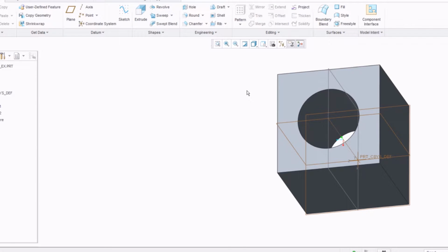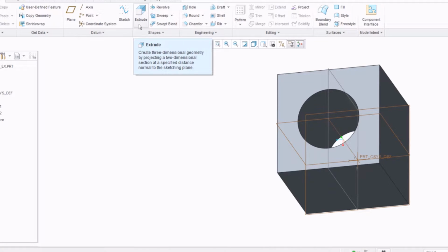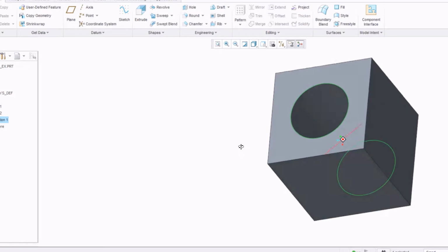Okay, so I've shown you the first way of extruding, but there's actually a second more useful way. Which actually, I think I showed it to you by accident, but you'll see it here. The first way I did with a sketch and then an extrude, and you'll actually see that it created 2 features in the tree on the left. The second time, I completely forgot to let you know I was doing it. I actually just clicked the extrude button and then started making my sketch. So basically, the difference between the two is this. When I click the extrude button, it's automatically going to say, hey, I need a sketch. So it's going to prompt you to create a sketch. If we go to the model tree off to the left and click the arrow next to extrude, you'll actually see section 1 is that sketch.